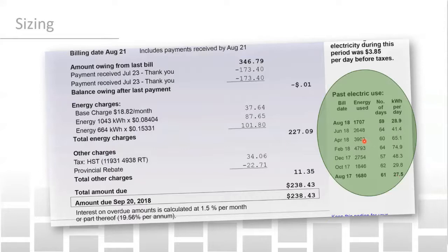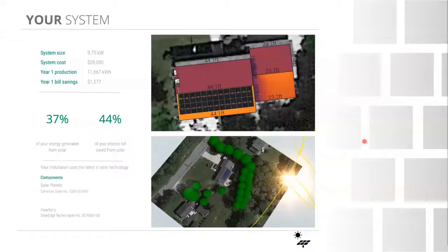Because under a net metered program, some utilities won't pay you for more power produced. So if you end up with a net credit, so I've produced more than I've consumed, that gets washed. Or in the case of Nova Scotia Power, who will pay you, they don't want you designing systems that can produce more than 110% of your consumption. So very important factor in design.